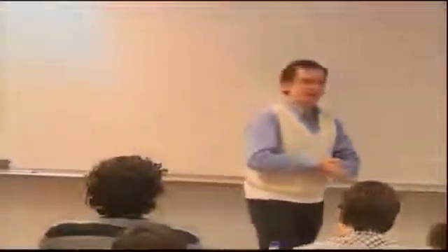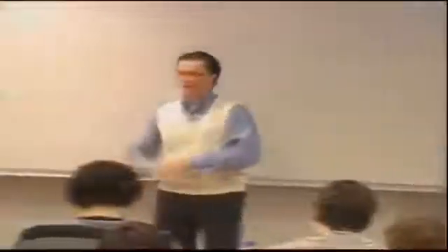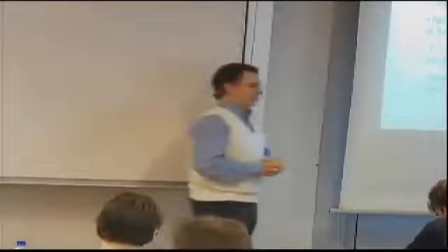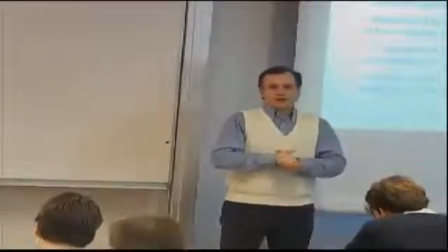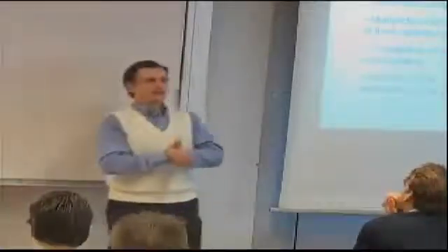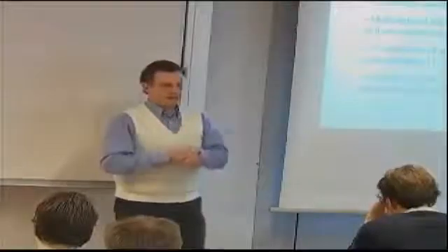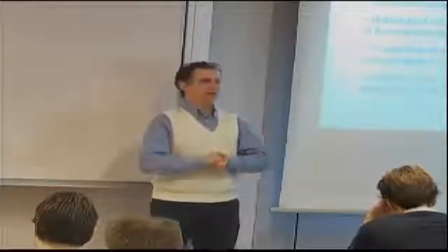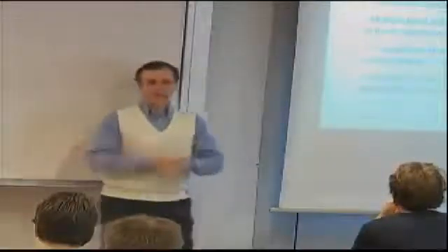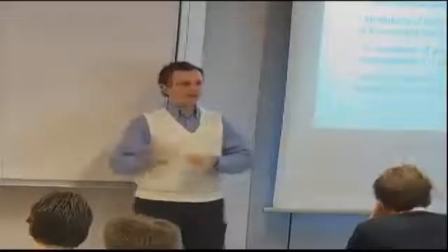Today we'll also do engineering by compromise and voting engineering. You'll see if we can design something by voting and democracy, whether democracy is a way of designing structures, which we'll do in a little bit. We were talking about, we finished the classical laminated plate theory in terms of being able to calculate for a given laminate the stiffnesses, and I use the plural because we have the membrane in-plane stiffnesses and the bending out-of-plane stiffnesses and coupling. And then based on those and applied loads, you can calculate strains and curvatures. And then we talked about failure criteria, which is the next step. You use all these strains and stresses to try to predict failure, because ultimately you want to design these structures for lower weight or for a bunch of other attributes that we will be covering today briefly.